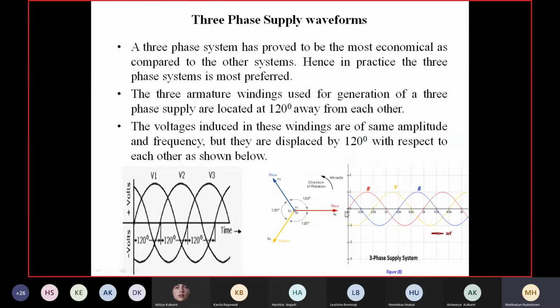Then what is the phase sequence I said? It is a sequence in that order peak of a wave appear. First peak when I move from time plane, here if I start my journey, I will see first peak is red, second peak is Y, third peak is B. So to get this by vector, if I stand here as an observer, vector R goes forward, vector Y comes to me and vector B comes to me, which I have seen as red gone, yellow has come to me and blue has passed away from me.